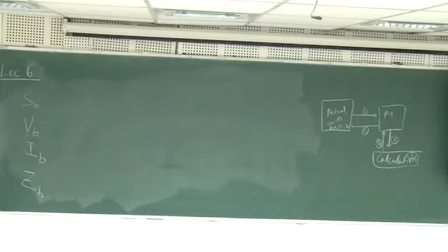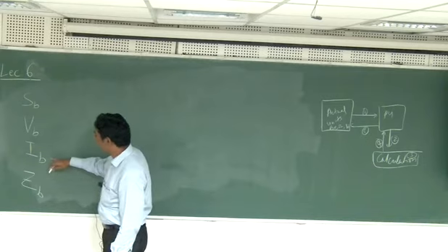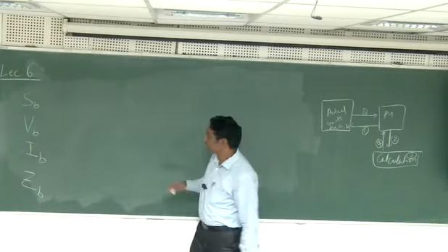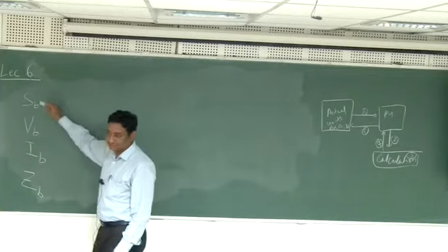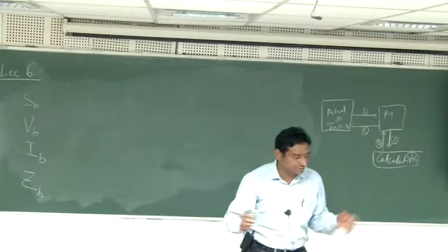So if I choose these 2, first I will write down the expressions. How do I express the current base in terms of S base and V base? Since I know V into I is P, think about DC quantities because these are only base quantities, they are all real numbers.